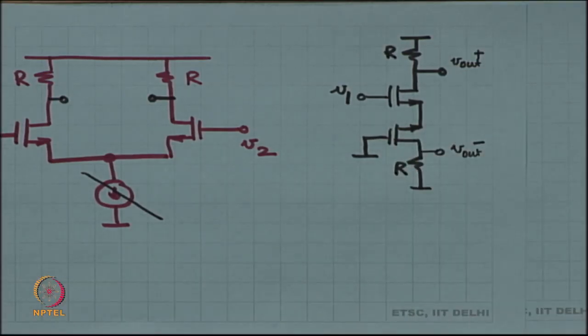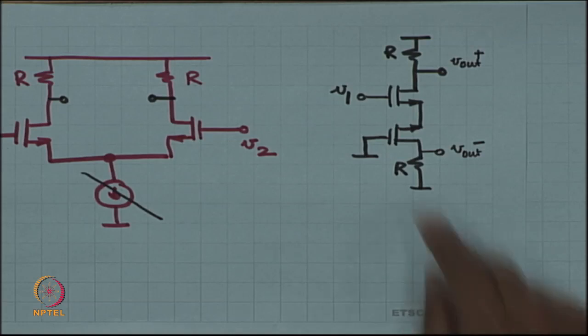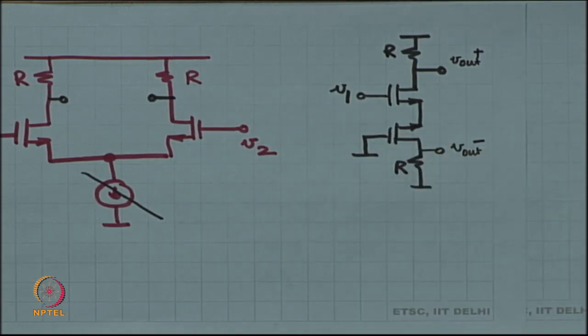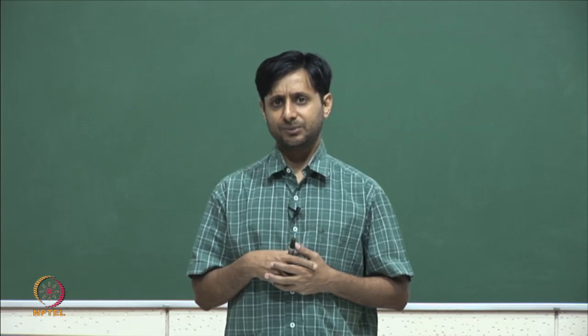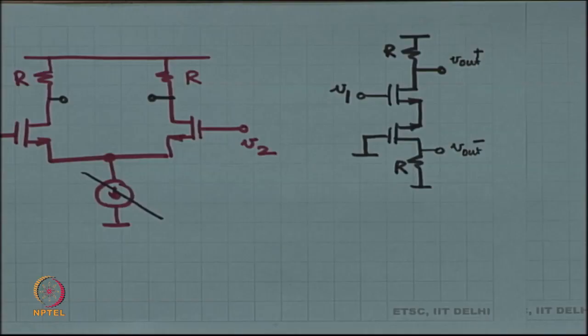And naturally you are not comfortable drawing this MOSFET upside down. It is very disconcerting. If you want, you can convert it to a PMOS. In the small signal diagram, the NMOS and the PMOS are identical. So, it is okay to change it over to a PMOS, nothing significant is going to happen. It is after all a small signal circuit, all right.